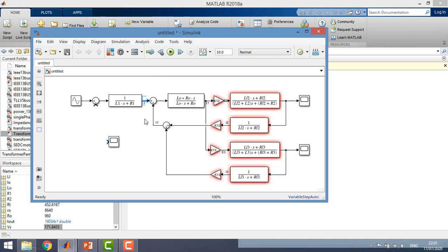and the total current flowing in the primary circuit is the summation of the current transferring energy to the secondary and tertiary windings, in addition to the current feeding the iron losses, which is multiplied by the shunt admittance to produce the induced EMF in the primary winding.